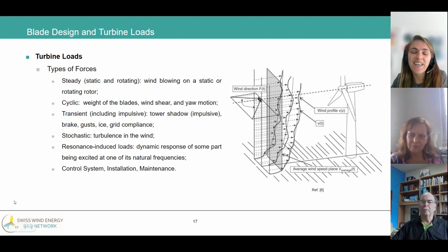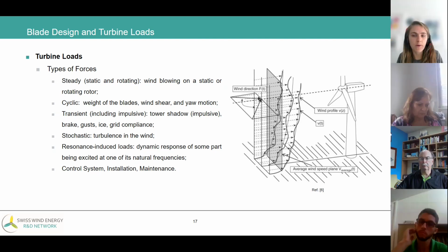Yes, thank you, it's a valid comment. The blades usually have some sensors along the radius, not in so many positions, but two or three, and it depends. Offshore turbines usually have more sensors than onshore turbines. Why? Because you will be controlling how the wind turbine is behaving, and if suddenly you see a vibration at a weird frequency that only one blade has, you can go and do this kind of inspection.